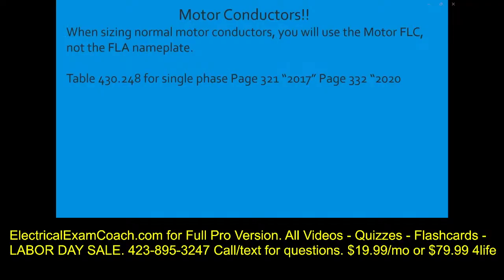So the first thing that we do when we get to this table is we read the black bold heading. It says full load current in amperes for single phase alternating current motors. Great, I feel like we're in the right table. I would go ahead and take a moment, if you can, and highlight that right there where it says full load current, and then highlight the words single phase. Okay? Highlight full load current and single phase.